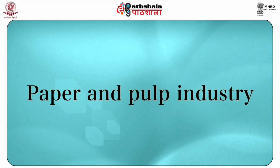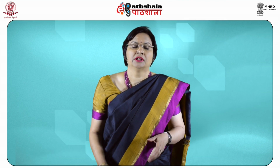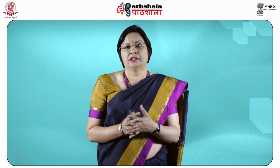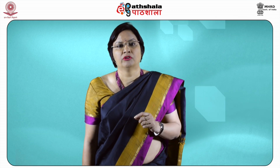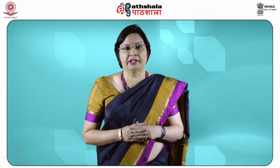Another industry that I would like to mention is the paper and pulp industry. The waste paper from the paper industry can be recycled or reused. The suspended solids in paper mills can be removed by sedimentation so as to reduce water pollution. This process of sedimentation will result in the settling down of particles under the impact of gravity, and then they can be removed from the base of the tanks. The chlorine-containing bleaching agents can be replaced by other pulp bleaching agents which are comparatively environmentally friendly, like hydrogen peroxide, ozone and oxygen.